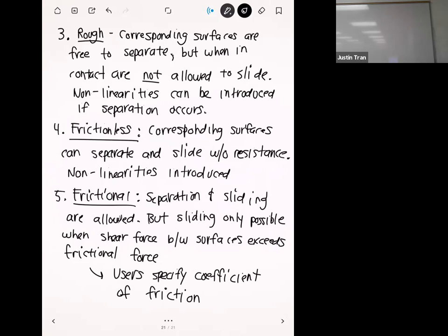And so if you tell any professional engineer, they're going to think you're crazy. That's not to say that you can't do it. It is possible to get convergence, but you probably have to put it as a pretty light loading situation. Even then, you at least want to see 3 or 4 different plots on the road to say that it's going to converge. Generally, the lighter the load that you have, the less non-linear stuff is going to happen, and so it becomes easier to converge.